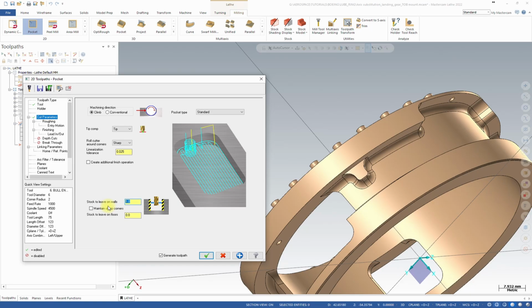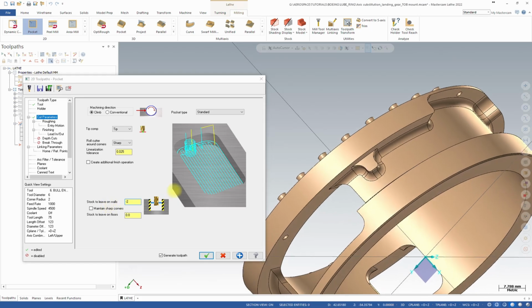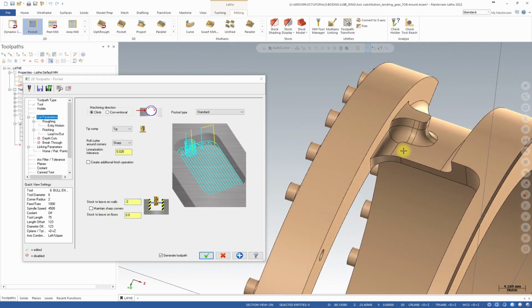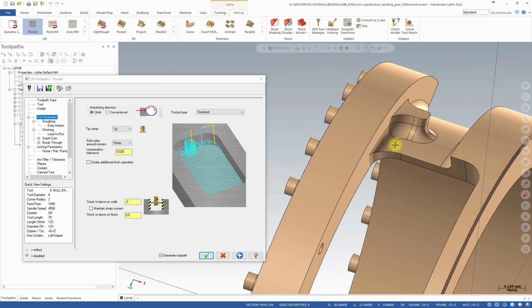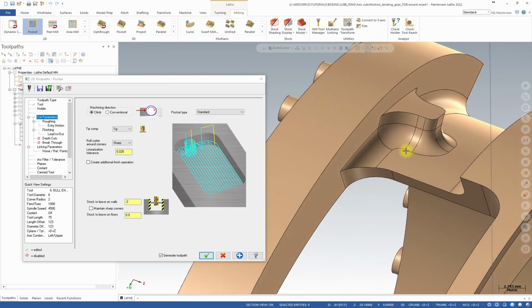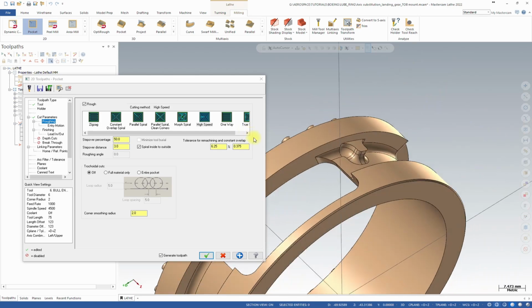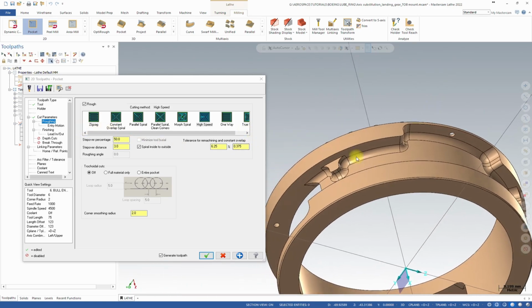To cut bigger than your chain, you need to put a minus value, and in this way it will overcut the pocket. Because our chain is on that edge, I want a minus value so it will offset the fillet. Because the fillet is 2 mm and we have stock to leave at -2, it will go bigger. Standard cutting method.